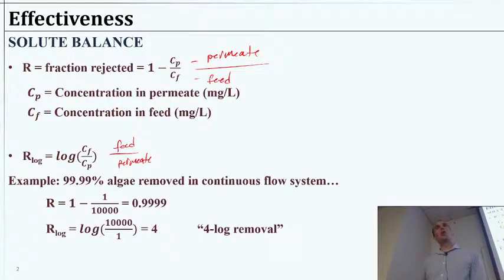And usually we're targeting something more than just 90% removal. Usually we're trying to say, hey, we need to use this membrane to really make sure that the water is clean to drink. So we're going to aim to get 99.999% of viruses out, right? We might be okay letting 1 in 100,000 through as a kind of standard.